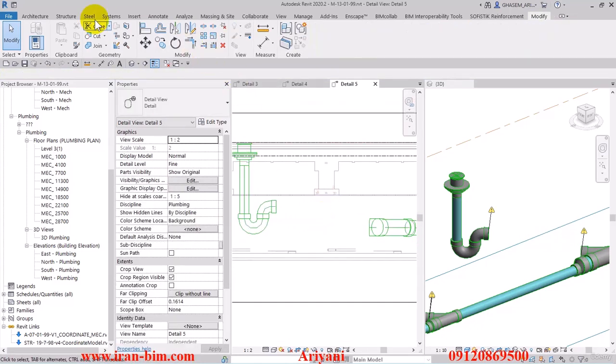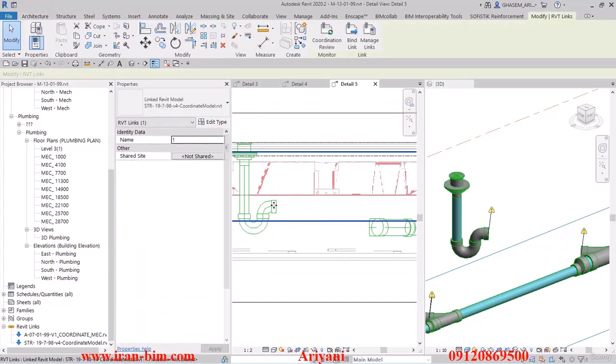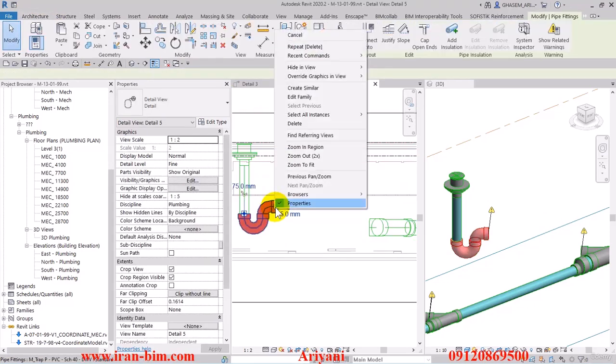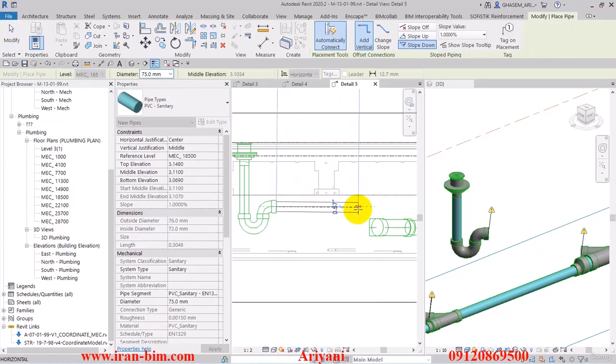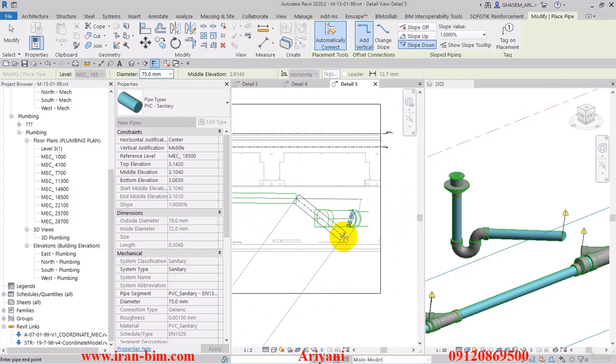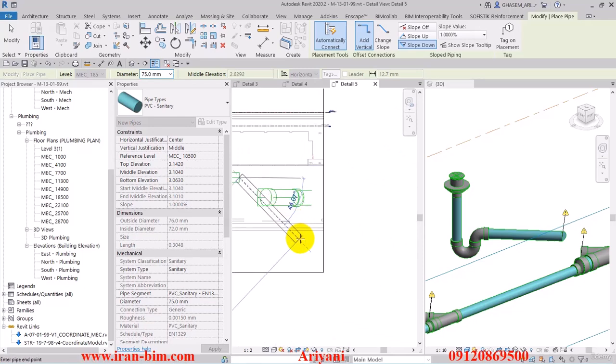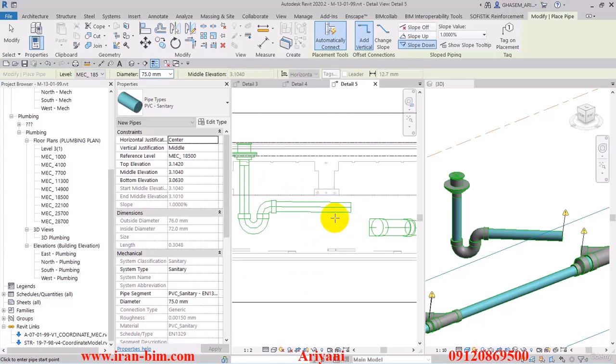It's fine, I can go over here and right click on this piece that we have and select the draw pipe option. Then I'll use a 1% slope and then a 45-degree angle. Alright, now as you can see, we don't actually get the 45 degrees from the angle because we've already drawn the piece using a slope.